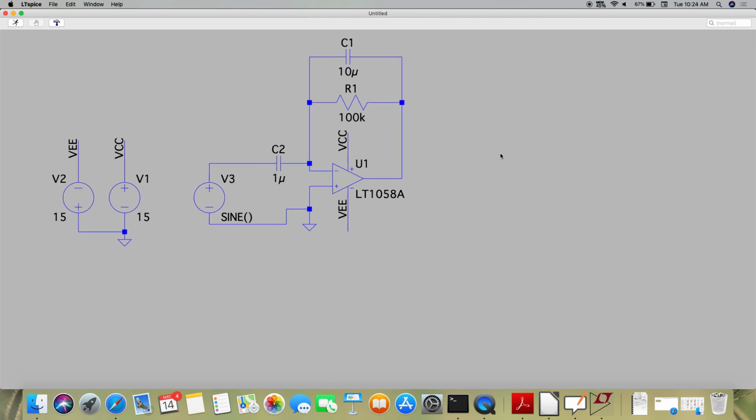So after this, what do you think? What should I do? How to run the simulation? There is a run symbol, but the only problem is that my simulator does not know which analysis has to be run, transient or AC. I need to tell it till what point it has to be run. Like if I want to run transient and see the signal till 1 microsecond, then I have to tell it to run the simulation till that particular point.